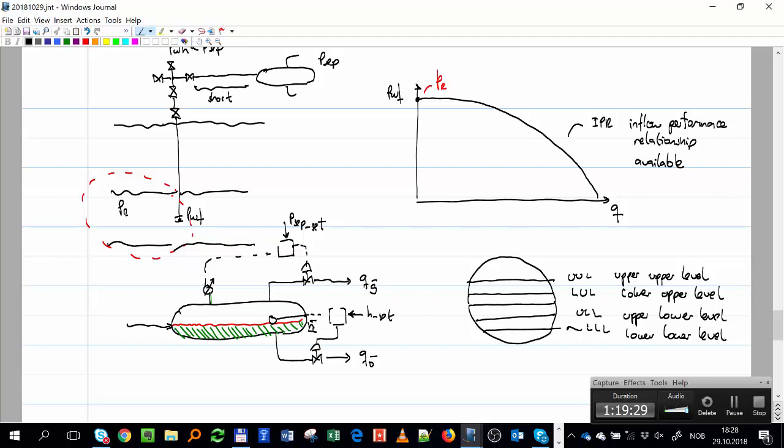So that's why I have these two, like a band. When it reaches here, I have an alarm or a certain mechanism, and if it goes below that number, it shuts down the production, because then the separator won't manage to separate and you will have oil and gas.